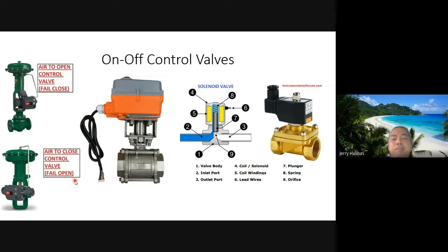I have seen ball valve types that are motor operated control valves, in dryers, oven type dryers. When the oven type dryer closes, they usually use these because they are cheap. For those who cannot afford a pneumatic system, since they would have to buy compressors, they opted to use motor operated control valves. On and off. I don't know, I have not seen a proportional motor control valve; instead, most are pneumatic.